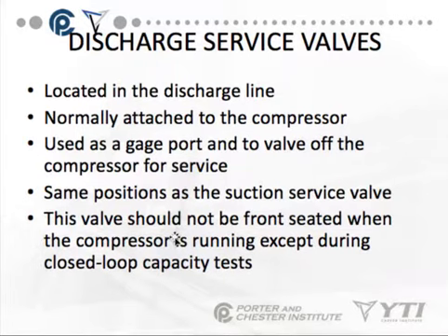Discharge service valves are located in the discharge line. They're normally attached to the compressor. They can be used as a gauge port or to valve off the compressor for service. They use the same positions as the suction service valves. Do not ever front seat a discharge service valve when the compressor is running. If you front seat the discharge service valve with the compressor running, you'll blow up the compressor. There's no place for that refrigerant to go, and it will start blowing out the valves and bearings in the compressor.